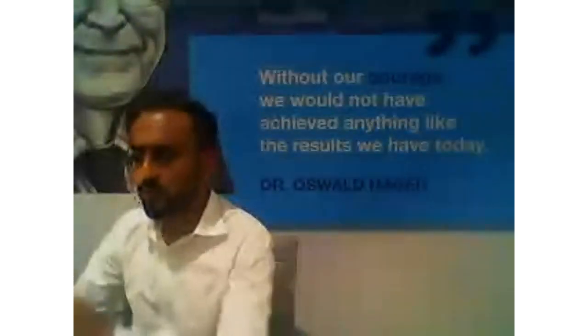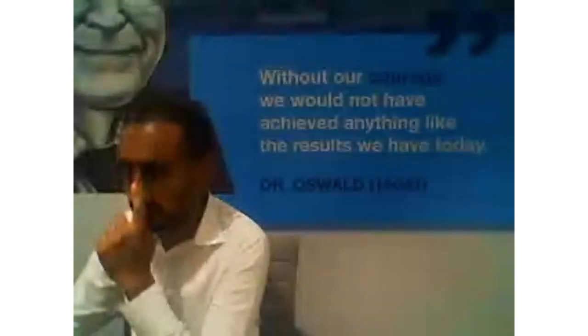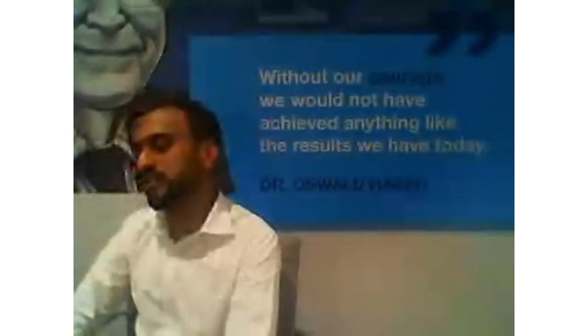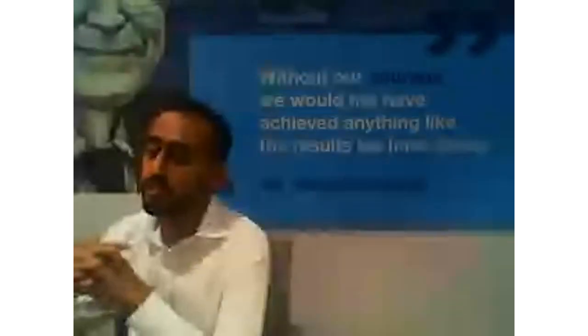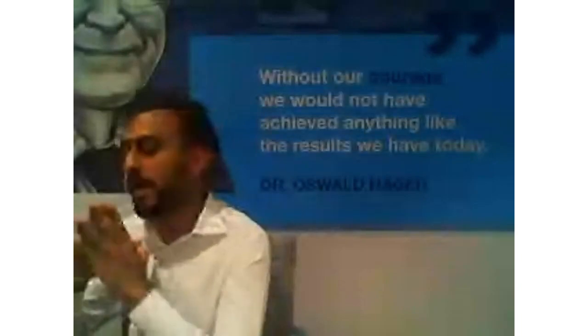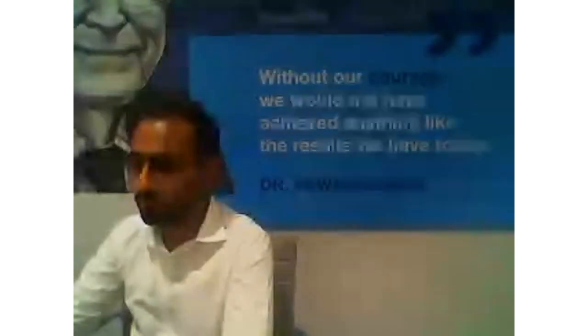Okay, so which one, ICC 3, ICC 2, ICC 1 is the maximum? ICC 3 is the three-phase short circuit. So it's the maximum short circuit which you can have in a network. It's basically between all your three phases. ICC 2 is between two phases, and ICC 1 is between a phase and a neutral. So ICC 3 is the maximum. Okay, I hope that answers your question.